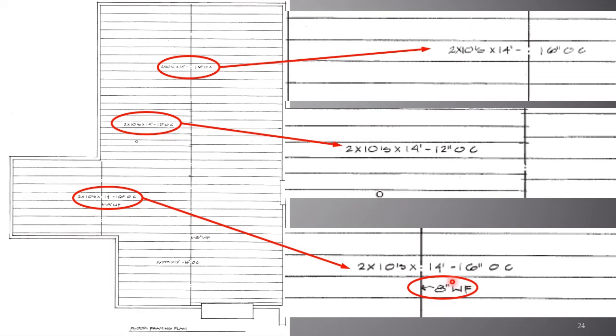Notice it calls for the 8-inch wide flange beam, and this runs down the center of the basement, and these wood joists rest on the beam. Now, why is that? Well, as you recall, we just talked that the maximum limit for a single piece of dimensional lumber is about 24 feet. And we know from prior discussion and assignments that the distance from here to here is about 29 feet.